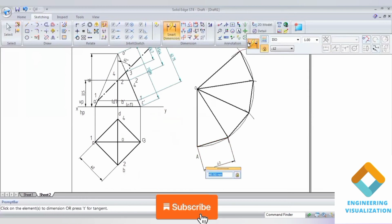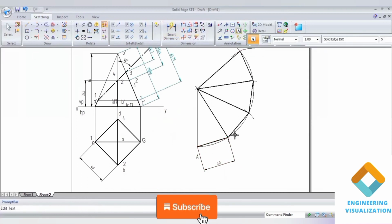So the dimensions we can measure and give the naming: capital B, capital C, capital D, and capital E, and A again. Now at the cut points we should mention the dimensions which I have already measured on the slant edge. For A1, the same length arc we should cut. Similarly for 2 and 4 it will be the same length, and for 3 it is the length which we measured. Go to arc by center and type that same radius.